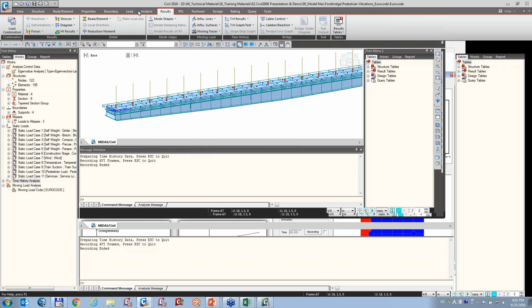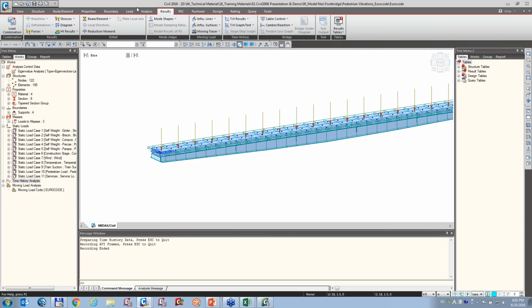For the Z direction, gravity direction combination, seismic loads, first of all, we can apply the response spectrum function for all the different directions, but the combination should be considered for different directions by the user.